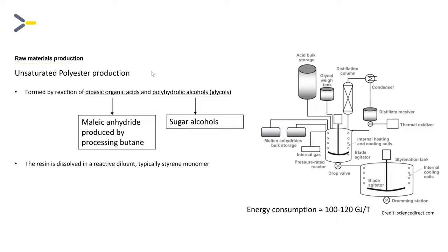Those numbers are very important because the normal split in the composite industry between resins and fibers is normally dependent on the process you use. For pultrusion, normally we use 75 to 80% glass, and the remaining is resin.